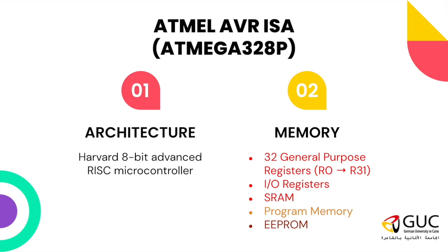Because as I told you, the SRAM or the data memory is volatile. If you unplug it, everything will be gone. However, the EEPROM is not volatile. So you can store important data that you want to retrieve even if you unplug your microcontroller inside the EEPROM.